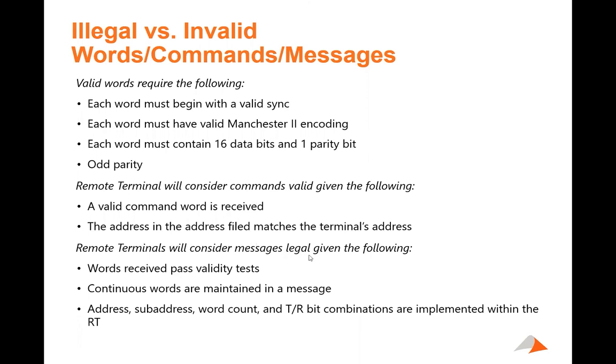Remote terminals consider a message legal given the following: the word received passes a validity test, so it's got to be valid; continuous words are maintained in the message, so there's no gap between data words, or between those and the command word or the status word; and the address, subaddress, word count, and TR bit combinations are implemented within the RT. If it's illegal, it means that the subaddress, word count, and transmit/receive combinations are not supported.